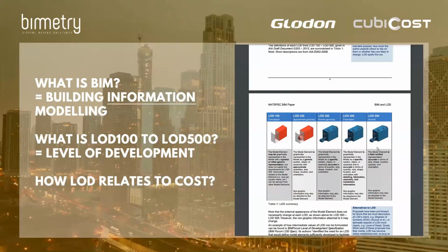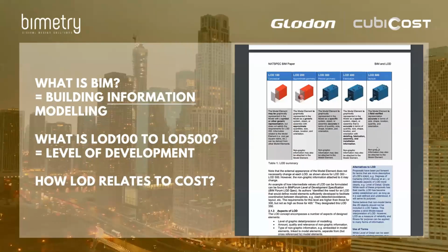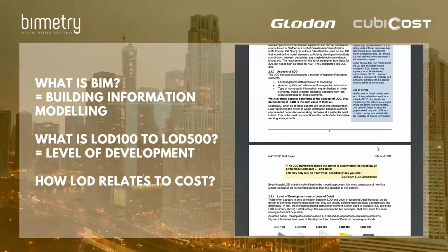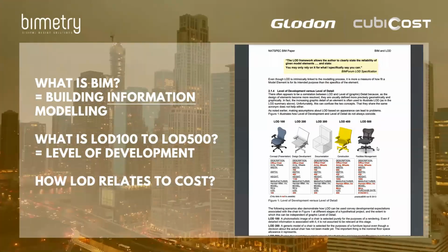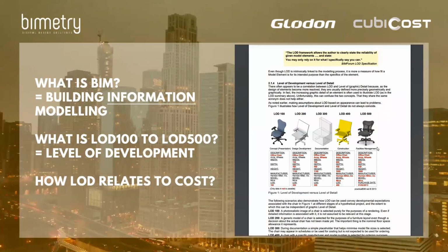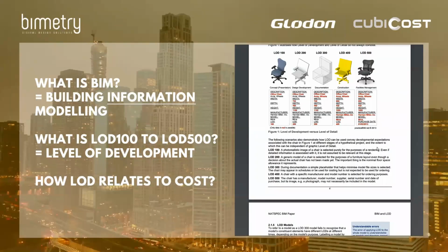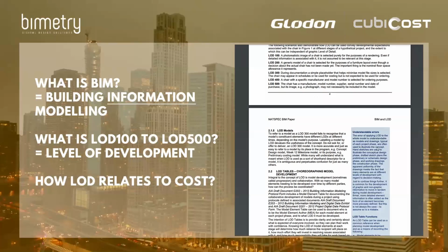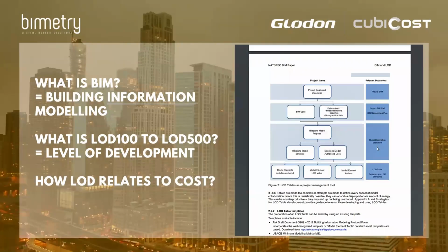As we mentioned, in BIM we have additional information, and one parameter of this metadata is usually cost. If we have prices in the BIM models, it depends on the level of development. In LOD 100, we can't expect to have cost parameters filled in yet. Usually, we make per square meter estimates based on the BIM model. In LOD 200, we can extract the quantities from the BIM models and give some approximations.